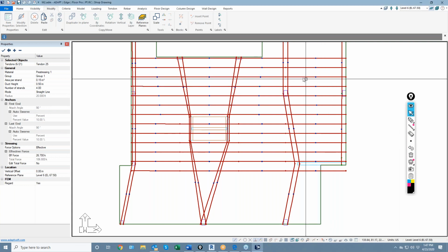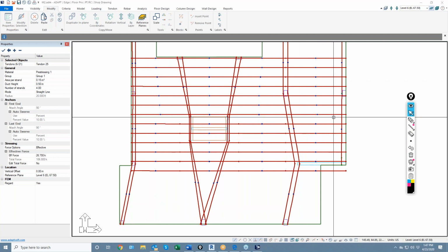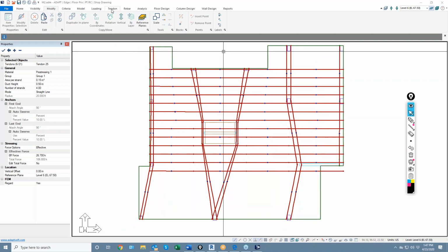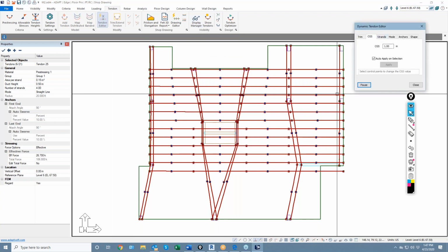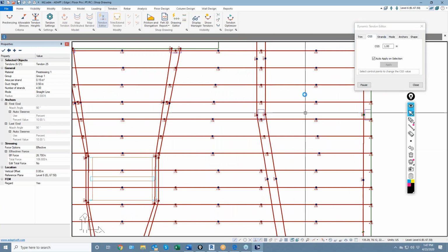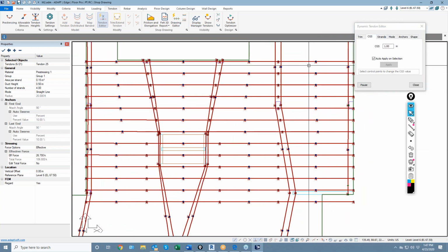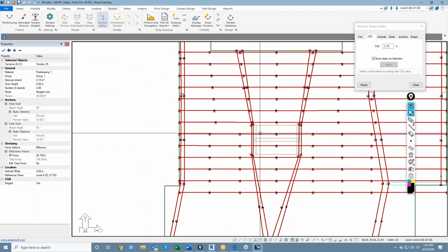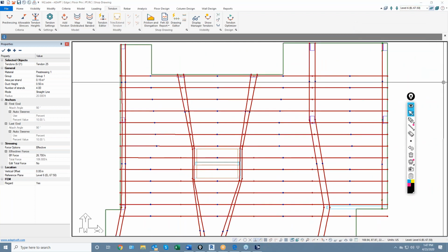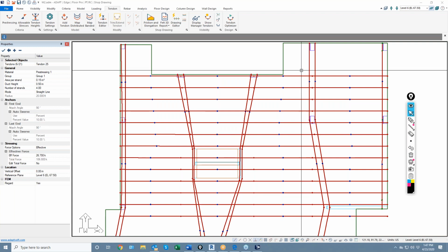If we assume that these end panels are unrestrained, right now you'll notice if we turn on the CG, if I go to tendon editor under CG, these are all shown as 1. So I say, well, I want to assume that that's unrestrained. We have some argument to make for that case. I could just come in and say these all need to be 1.75 and simply window select those cables and window select these cables. So that's how it would be handled from a modeling standpoint. Okay, all right, you're welcome, thank you.